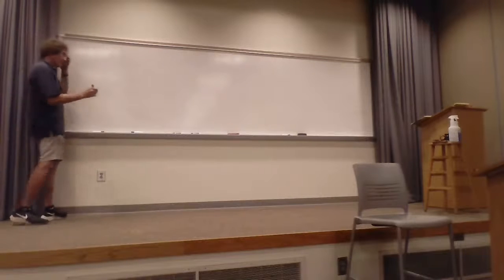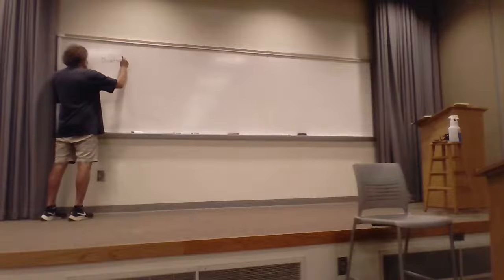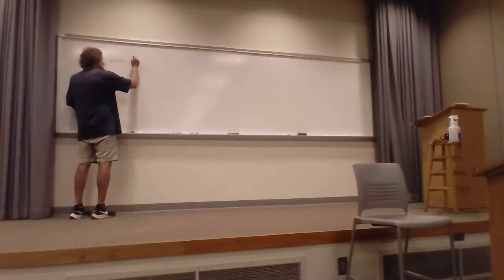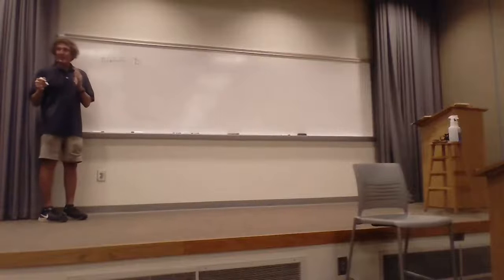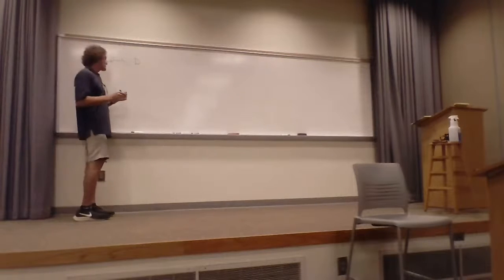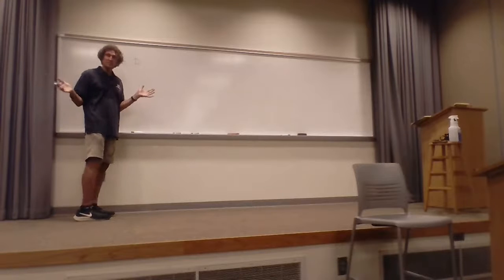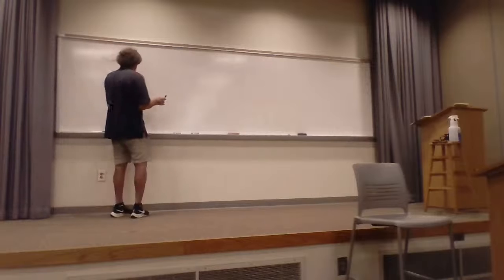So now the next thing is directivity. Please write this down. The symbol for directivity is D, and that's unfortunate because that's also the symbol for diameter in a lot of places. But it's D. That's directivity. It's unitless. Could be 0 dB, but it can't be mathematically 0. It can be 1.